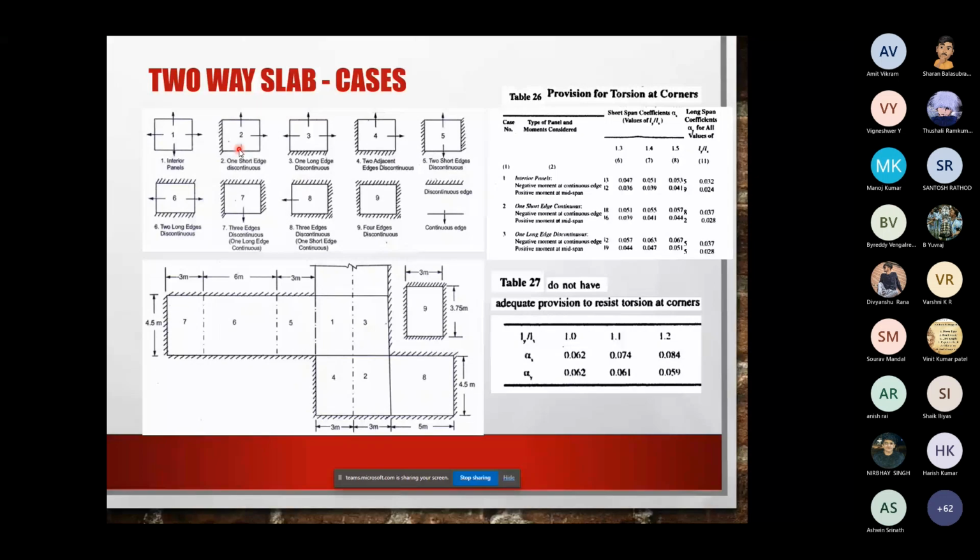So there will be a bending moment at the support. Basically, there is a transfer of bending moment across the support. Okay, that is the meaning of a continuous support. It's the same thing with the continuous edge. Only this is a slab, so therefore you have an edge instead of an isolated support, instead of a point support rather. That is the only difference.